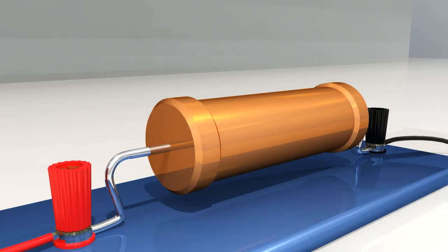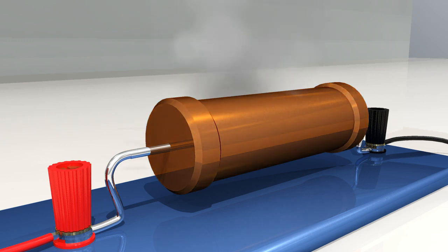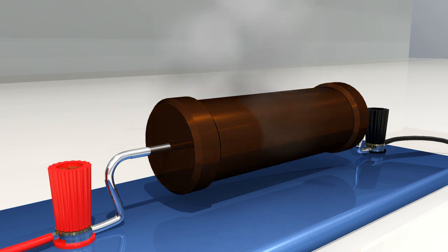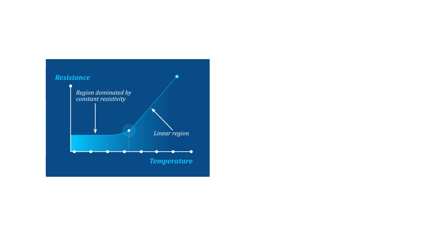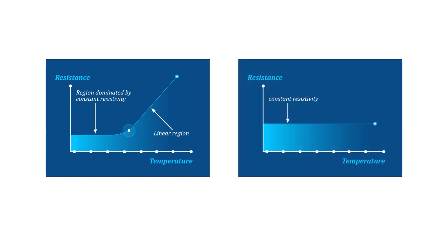Since resistors resist the flow of electric current, the energy they consume is converted to heat. For that reason, each resistor has an upper limit of current it can carry without being destroyed, and that parameter is related to both the melting point of the resisting material and its ability to conduct current. In the real world, the resistivity varies with the temperature of the material. In our simulated experiments, we will assume ideal, constant resistivity materials in our electrical elements.